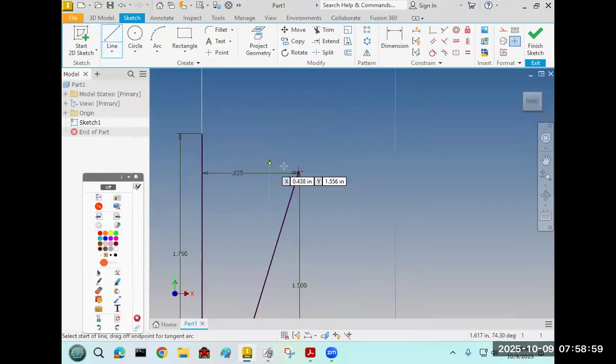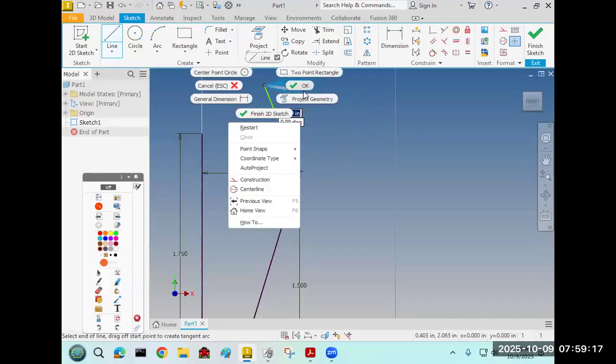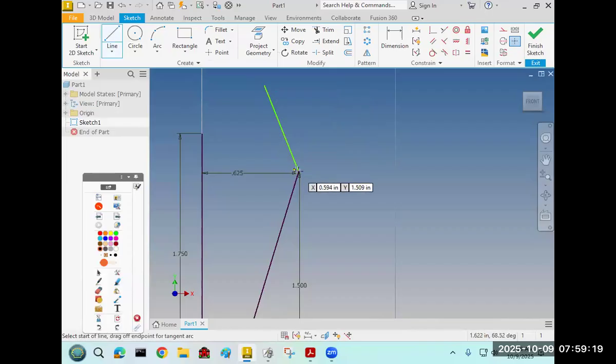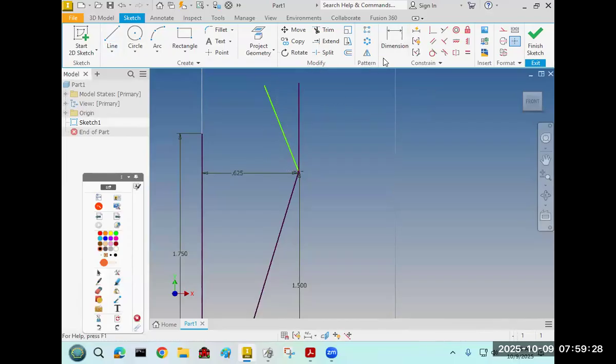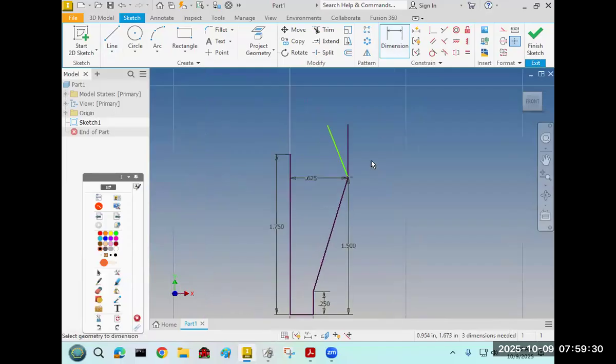We need a line that goes from this point, and you can get a soft snap here, that's fine. But it doesn't have to be because we're going to connect it. In fact, here's what we'll do. We'll get one line that goes up just past everything, and then another line from the same point that snaps to vertical, making sure that the second one you get a click. Okay, and once we have those two, we can dimension the angle, which I don't think we've done before.